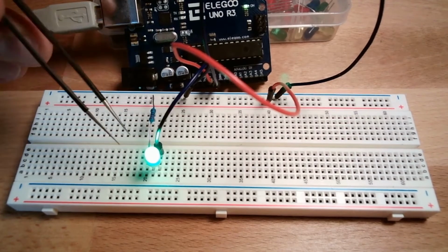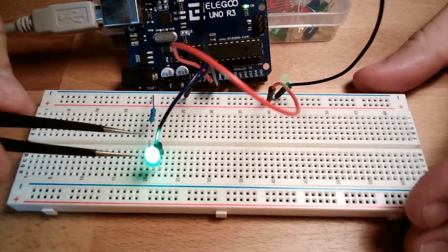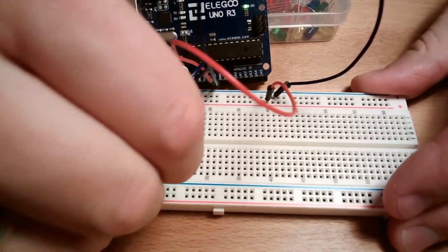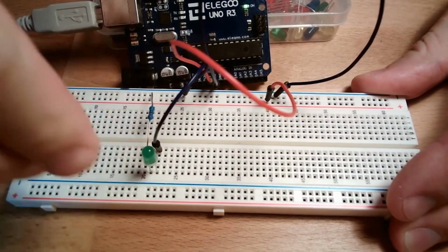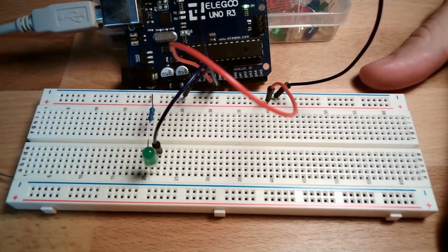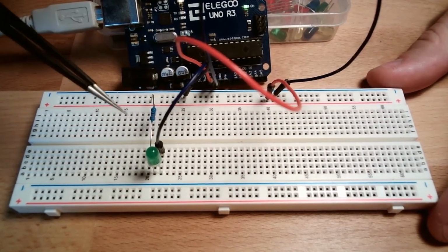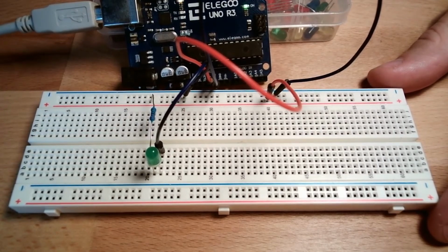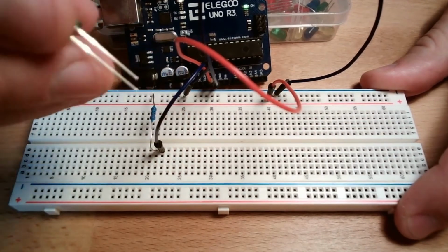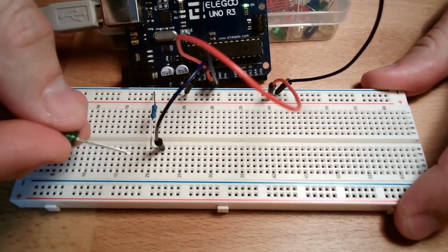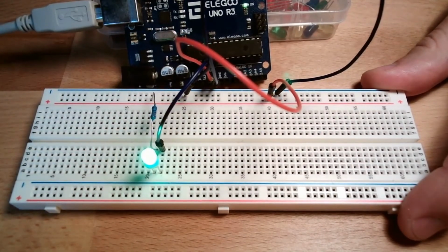If it's not working for you, please check if you maybe switched the direction. Now switch the direction of the LED, plug it in the other way, you see it's dark. This is because an LED is a diode, and a diode only works in one direction. You may be confused about plus and minus. Check if the long connector is at the plus pole and the short one is at the minus pole.